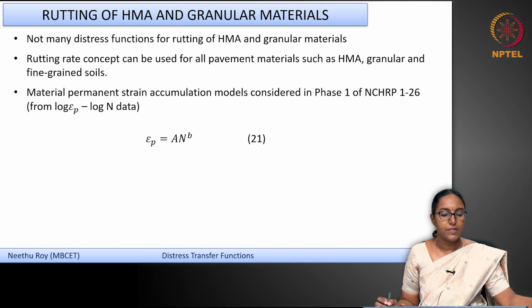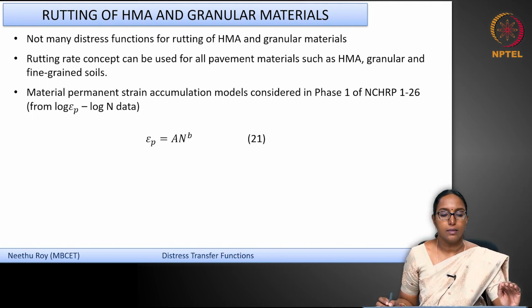Now, what we have discussed is the rutting expression as far as the subgrade rutting is concerned. So, essentially all other layers are not considered in that equation. You see the strains that happen on top of the subgrade, and it is related to the pavement surface rutting.